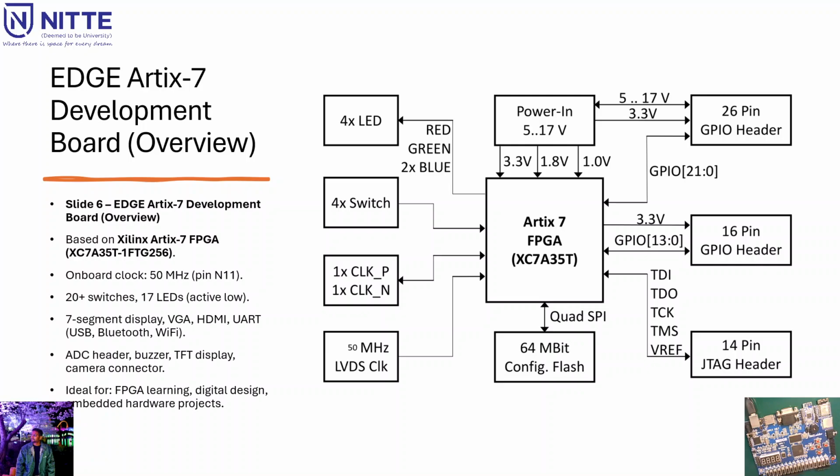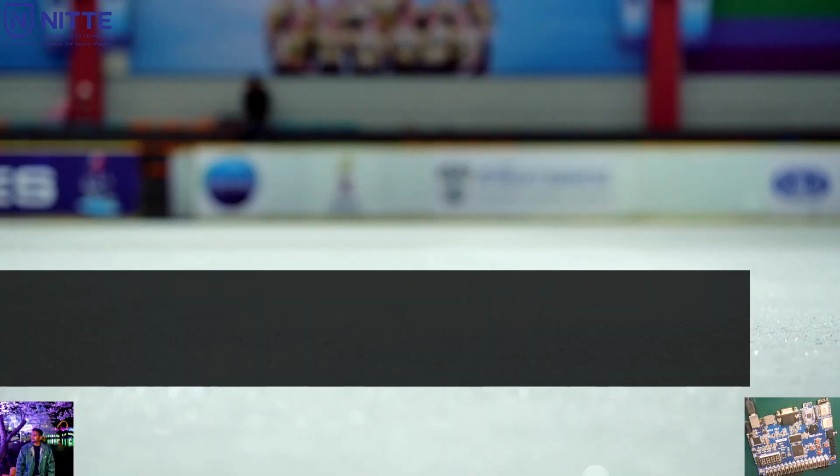You can also see the block diagram, which is represented here. It shows the voltage variation of the logic power in, which has 1.1 volt, 1.8 volt and 3.3 volt logic. We can use any one of them. And the detailed datasheet for the FPGA IC chip we are using is given in the description. You can go and download it and check for more detail if you want to understand this IC.